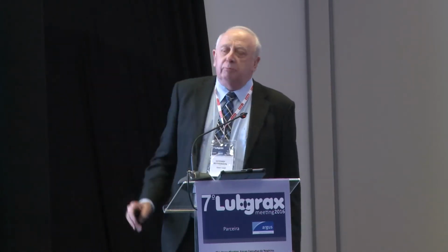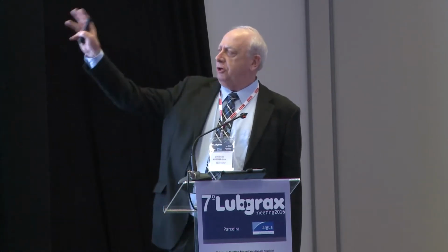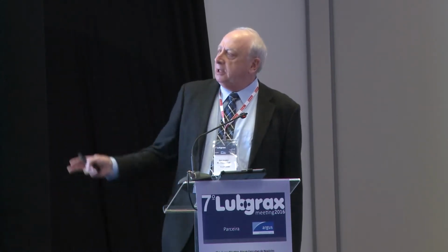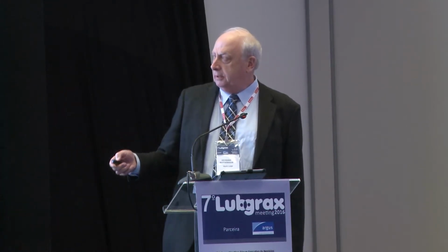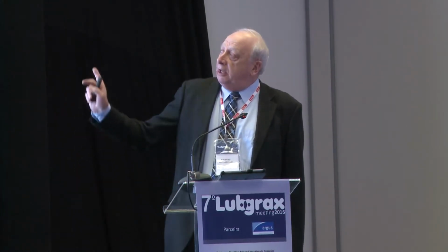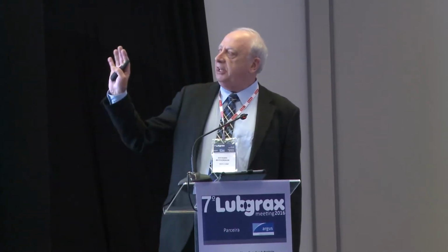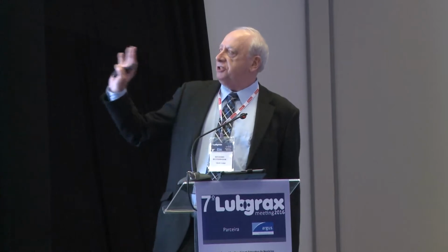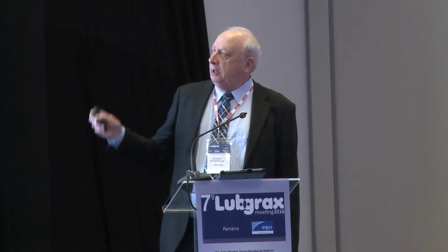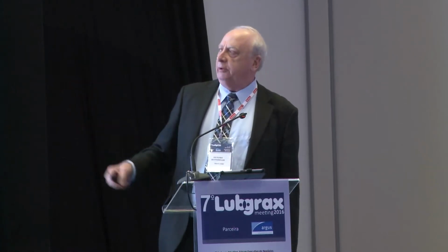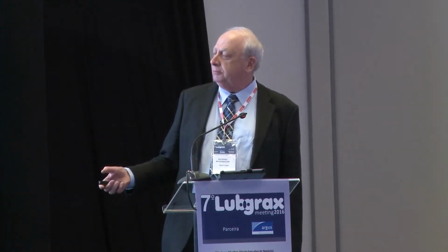Dirt, many sources. The air, the metal being worked, floors, all sources of contamination for the fluid. The workers themselves can be part of a problem. And very important, in all systems, when systems are cleaned out, unless a system is properly cleaned and treated before recharging with fresh fluid, the spoiled fluid is going to introduce contamination into the fresh charge.